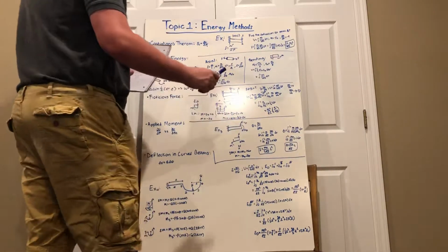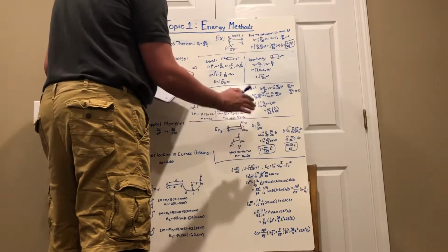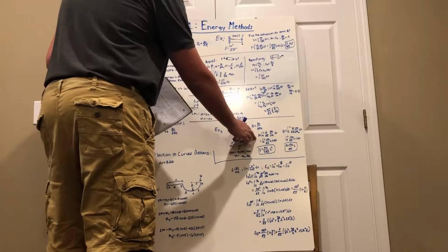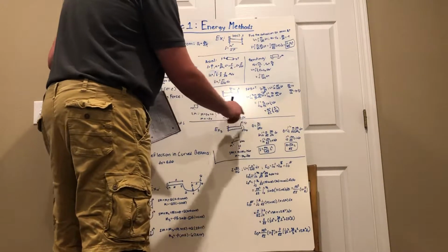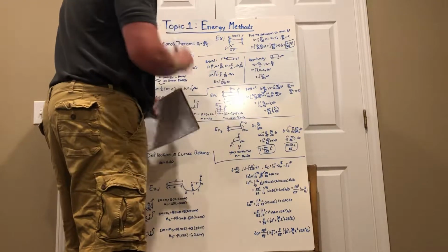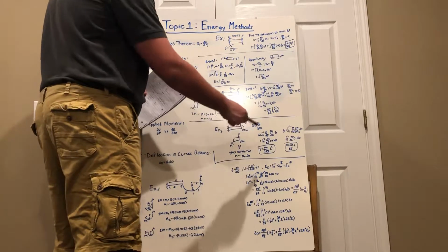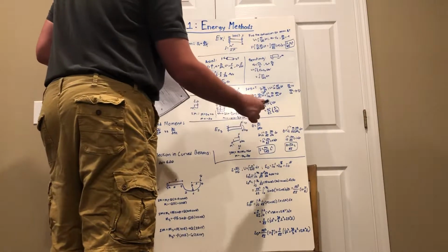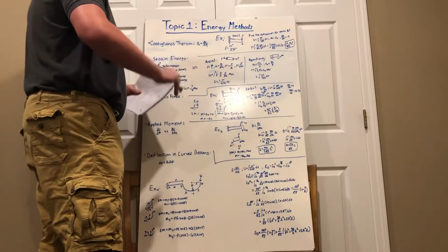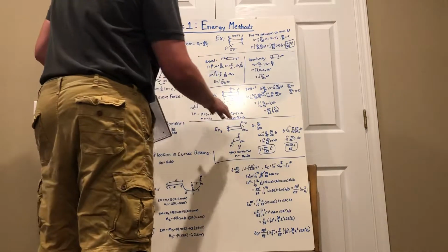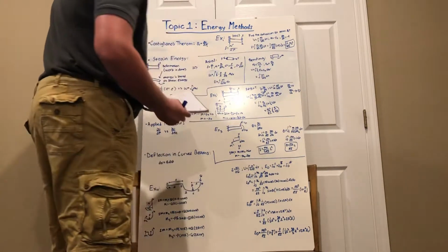So that being said, let's apply it to our normal force and find a distance, right? Applying it the same way, we're going to have our integral of M over EI times the partial of M with respect to this fictitious force Q times dx. Plugging everything in, we're going to have the integral from 0 to L of minus M over EI times x, dx, right? Doing all the math, we boil it down to M naught over 2EI times L squared. That's our deformation equation.